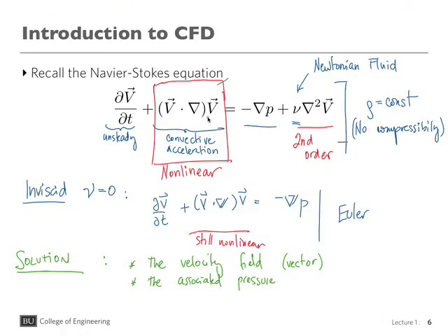Say you have a particular 2D flow where the velocity field is unidirectional and has only one component, so this term goes to 0, the nonlinearity disappears, and then you can solve the equation. There are very, very few cases of that. Like laminar flow inside a pipe, flow between 2 plates, or flow between 2 concentric circles. That's all. Very, very few.